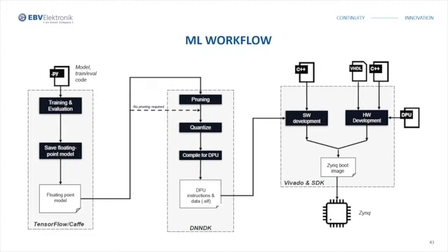actually the translation from the 32-bit floating point values from the training to 8-bit integer values, which will then later be used by the DPU IP. And then we have to compile our model, which will generate an executable file, which will then be understood by the DPU itself.